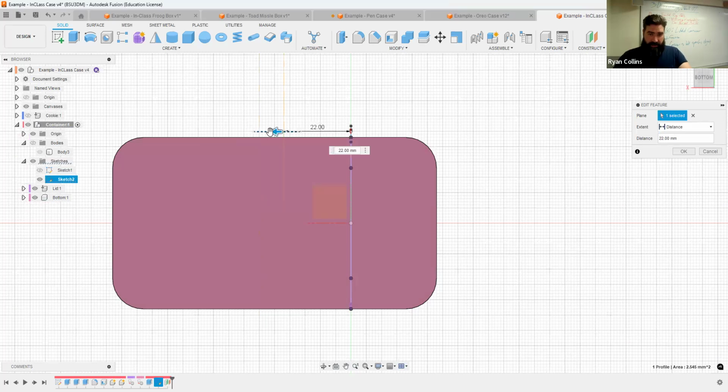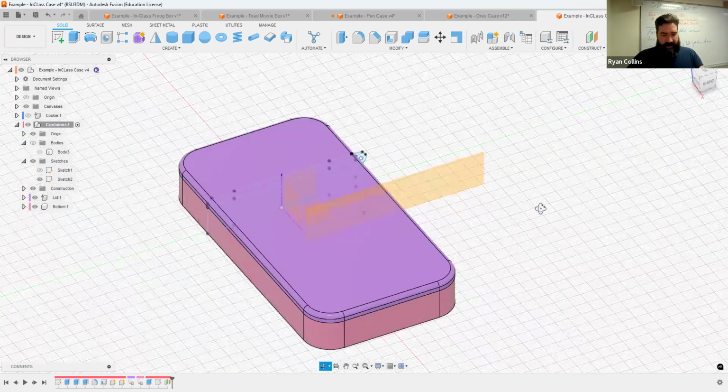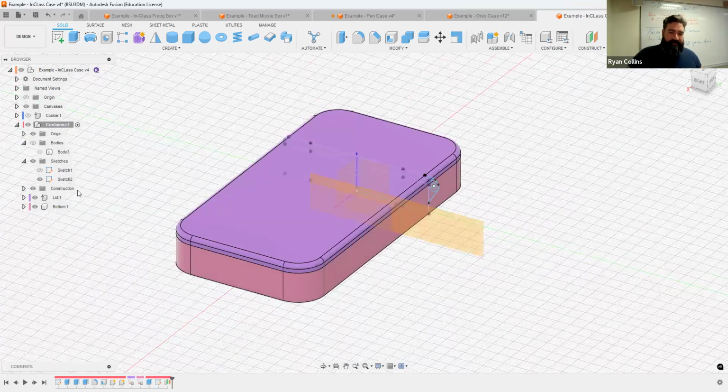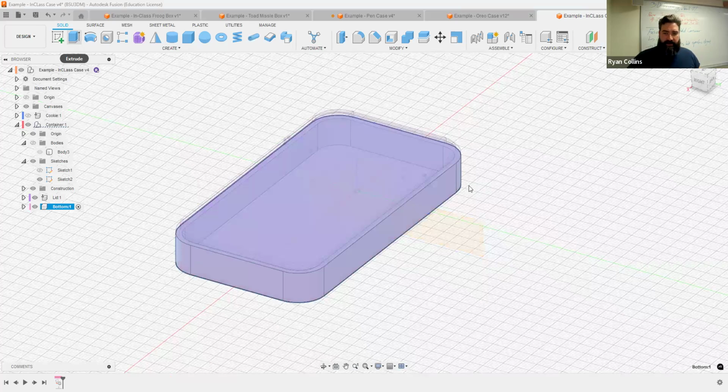Up there. Sure. Okay, whatever. We'll deal with it. This way, also, if you work off the construction plane, you can move stuff around as you need. Okay. So what I'm going to do now is, for whichever one I'm going to make, be it the lobe for the top or the bottom, I'm going to activate that component. So for the bottom, activate the bottom component, extrude.